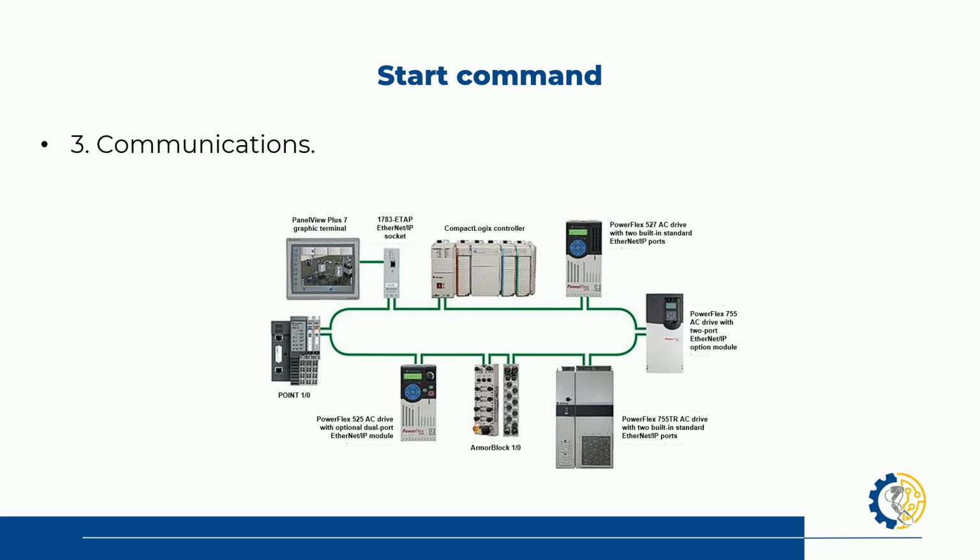And remember that we have our control part right here. That one cable is going to go to our switch. Okay, this is actually missing. Well, this is a ring topology. This is actually my mistake. This doesn't have a switch at all, so it's going directly to the other port in our controller. If there was a star topology, it would need the switch.